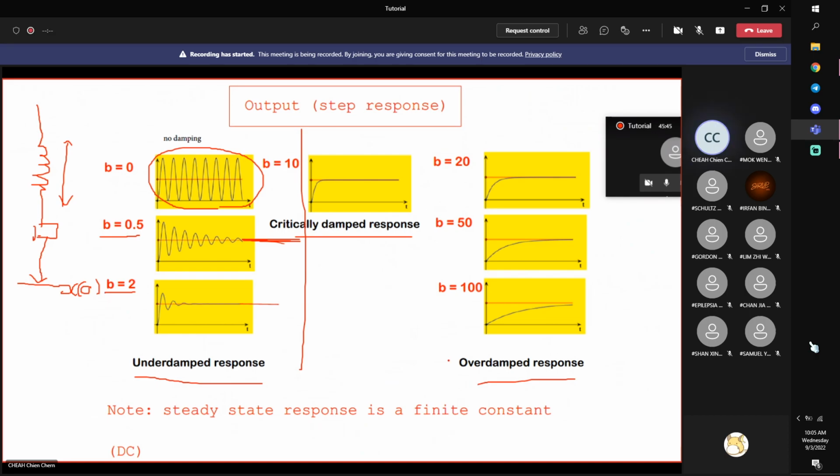Okay, and that is usually the case of overdamped. It will move very slowly. If you try to move in a swimming pool, you will never overshoot. If you do ice skating, the tendency of overshooting is very, very high. Now, critically damped is the boundary where your overshoot just disappears. That means you keep increasing your friction until a stage where your oscillation just disappears. It's called critically damped. After which we call it overdamped.